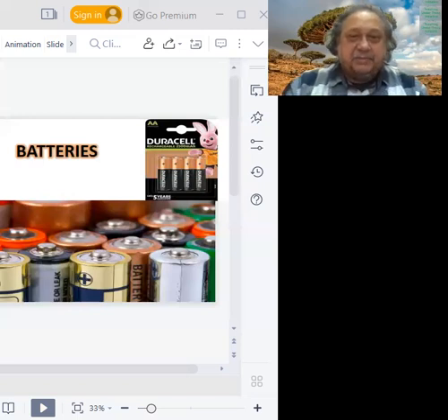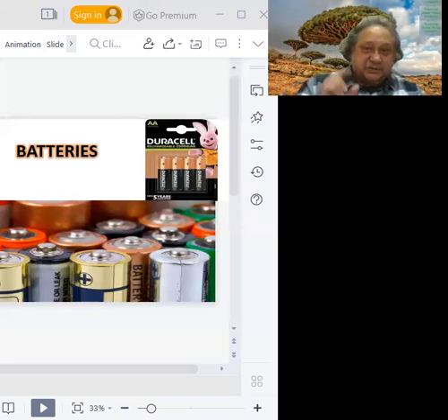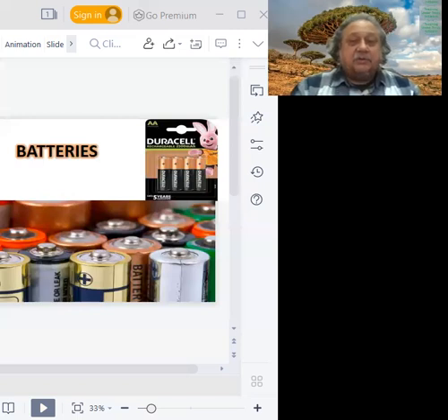In a practical system, we will often find that the anode is selected with the following properties in mind. We look at efficiency. We look at high coulombic output, amp hours, and then we also look at good conductivity, stability, ease of fabrication. What else?